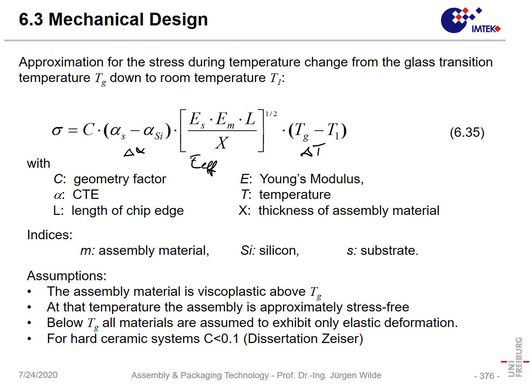And also we can say that in a certain way the stress increases with the length of the chip, while on the other hand we have that inverse effect of the die attachment thickness due to this shear strain effect.